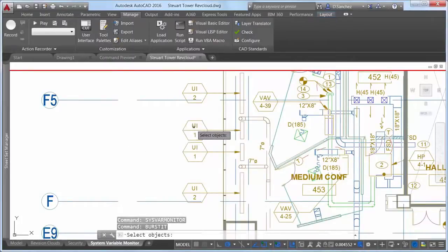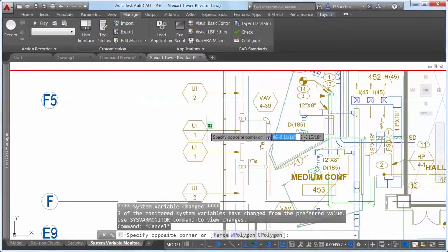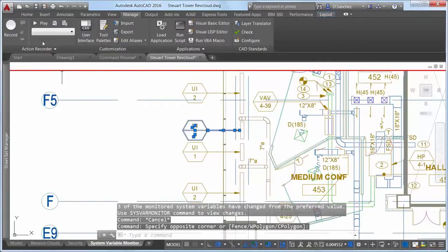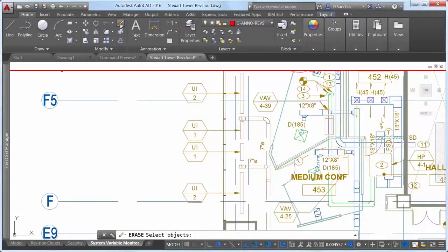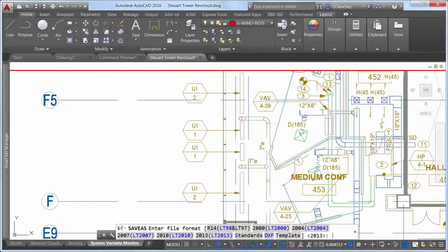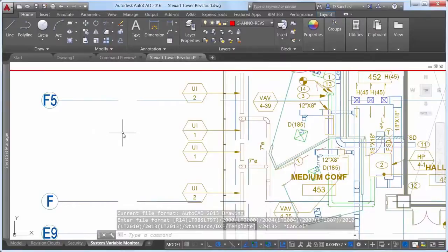to text. It seems to work well, but then you notice strange behavior. When you double-click on text, it doesn't open the text editor. You select the seemingly troublesome objects to try to erase them, but they won't go away. As a precaution, you try to save the drawing to a different name, but the familiar Save As dialog box won't even display. Your drawing isn't corrupt and your software isn't broken. That handy little Lisp routine that you ran happened to change a few system variables and didn't restore them to their previous and familiar behavior.